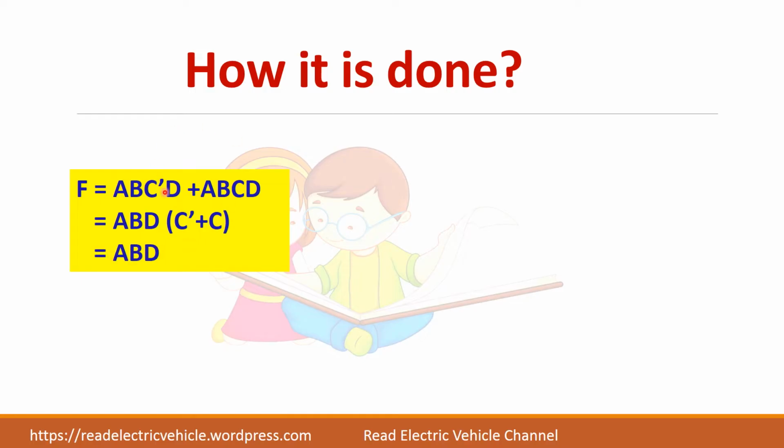So, you can see that the minterms are changing by only 1 bit. In this case only the C bit is different in both the cases. You can eliminate that bit in the final expression. So, according to this method, you have to identify 2 terms which differ by 1 bit.